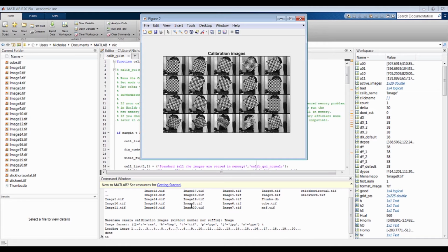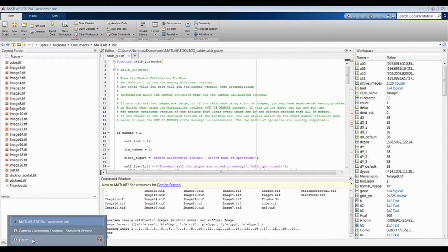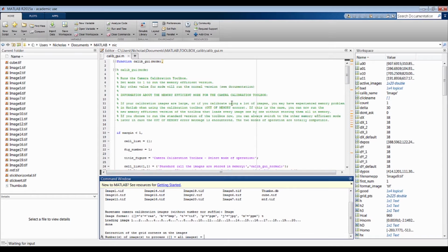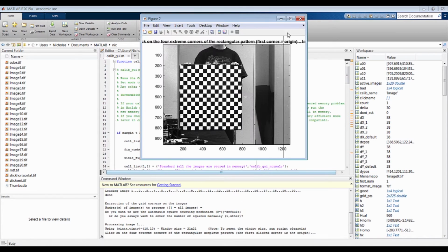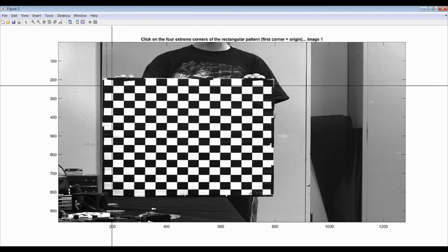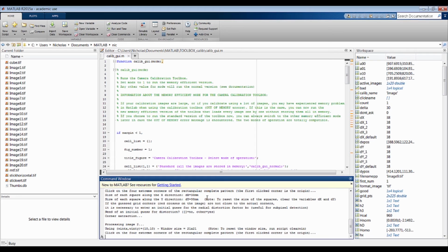Using MATLAB and the CalSci Toolbox, we begin to calibrate the camera. We start by loading all the images and then clicking on extract grid corners and giving the default answers. We can come back and recompile the corners if need be for errors later. With the first image up, we map out each of the 4 corners as shown here. It'll then ask for the size of the square, which for ours was 38 by 38 millimeters.